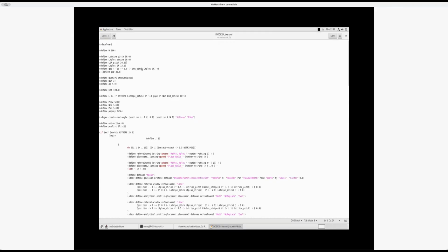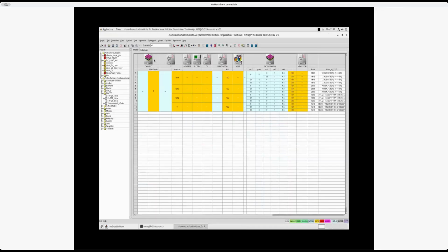What is interesting to note here is my parameter. I'm trying to find a good one here. So in my script, this is how I parameterize my script. That script could be completely executable if I define numbers everywhere. But as I mentioned in the tutorial last week, it's interesting to be able to make things parametric when it's easy, at least, so you can control it with the tool and change that parameter later if you want. The way you do that in the script is you have these @ with the name of the variable. And then when the nodes are being generated, these will be replaced by the real values. I'll close this for now.